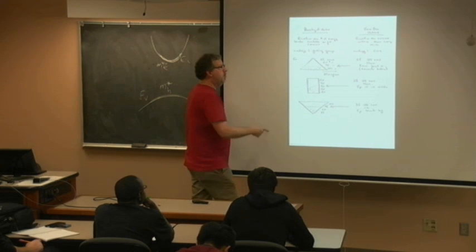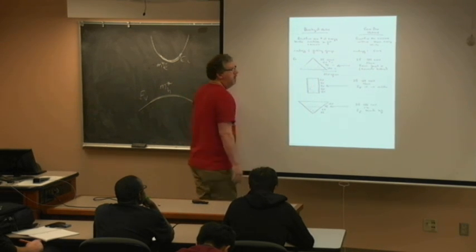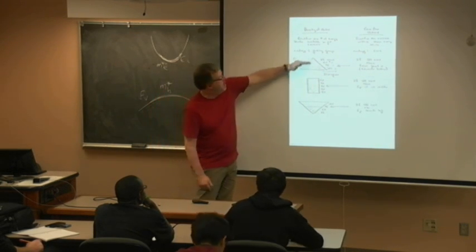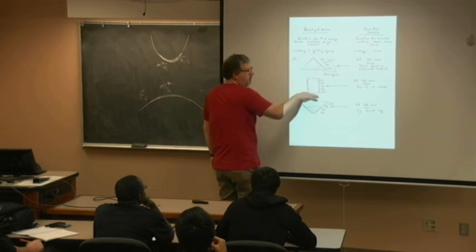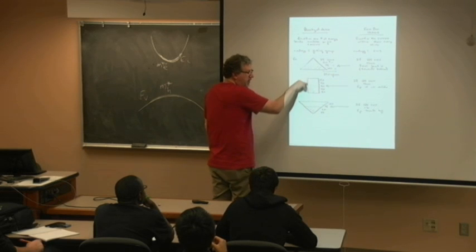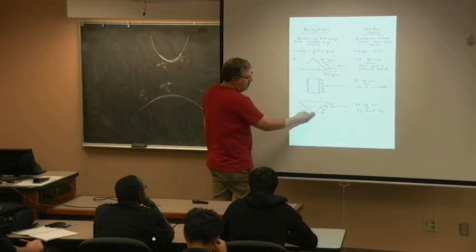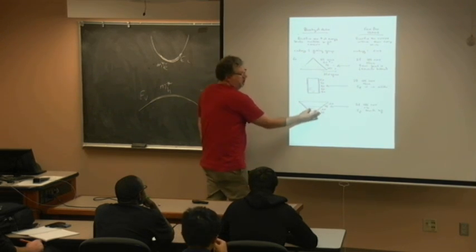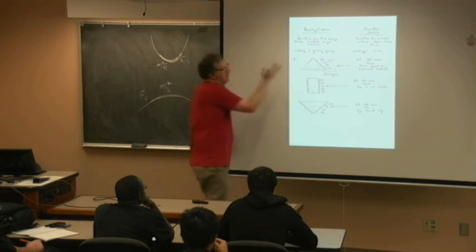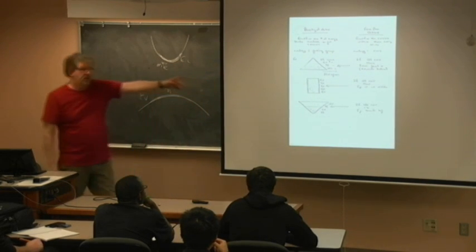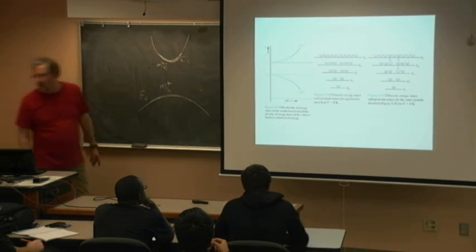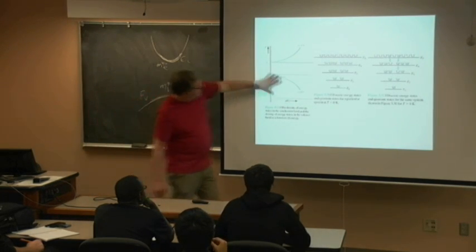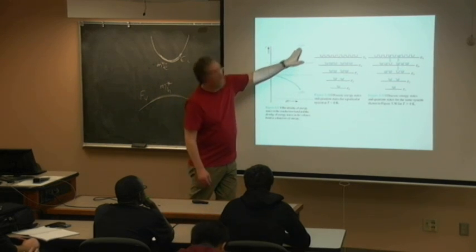My Fermi level is sort of, the probability of occupancy is 1/2. So it kind of tells me how filled it is. So here you can see this is weighted to the bottom. This is weighted equally, so it falls in the middle, and this is weighted towards the top because it's so shallow at the bottom. So they end up with 3 different Fermi levels calculated by that. Yeah, so here you can see the density of states showing, so this goes up parabolically.